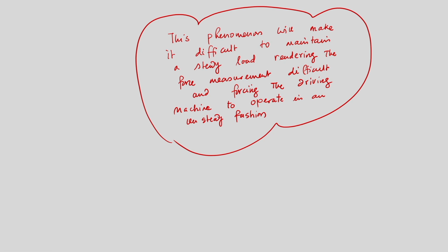So, we have discussed why the shaft power measurement is important in the context of fluid mechanics research. If you would like to measure shaft power, then the most common, simplest absorption type dynamometer is the Prony brake, and that is what we have discussed today. We have drawn the schematic depiction of the Prony brake, and then we have identified the different parts which are integrated with the system.